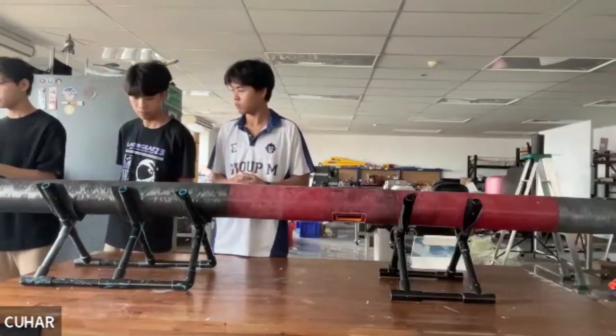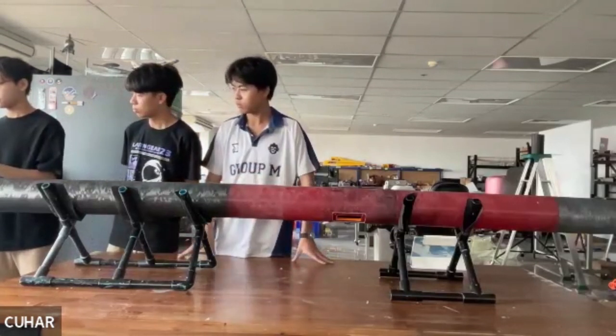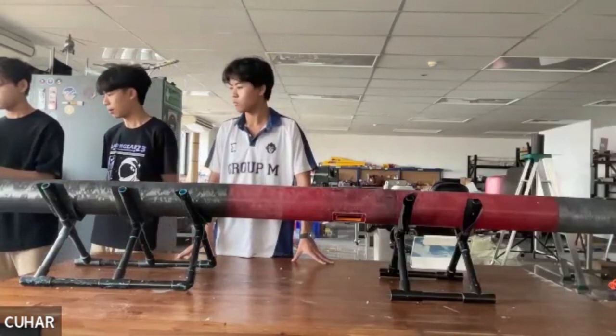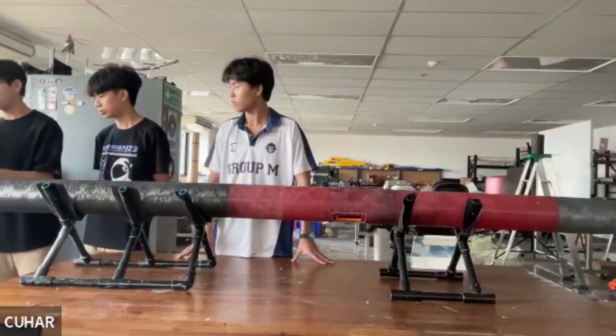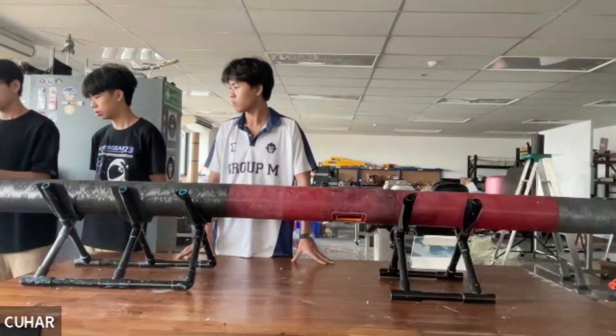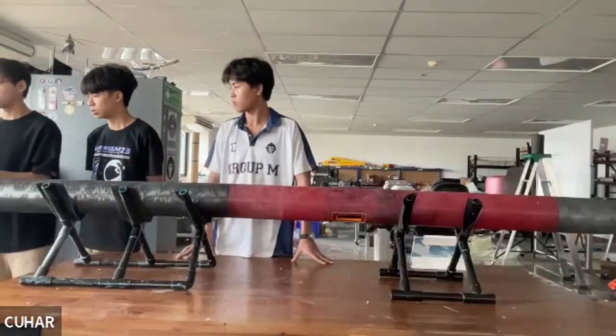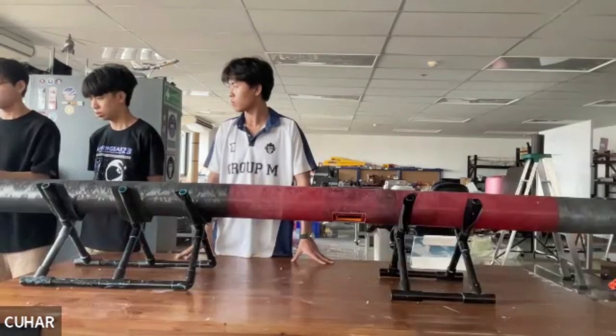In this design, we designed it to be a hybrid model. In the initial part, we have the tangent ogive profile, and afterwards we have a conical profile. We want it to be fully conical, but the inside also needs to hold the thrust plate so that it can take the forces of the motor.